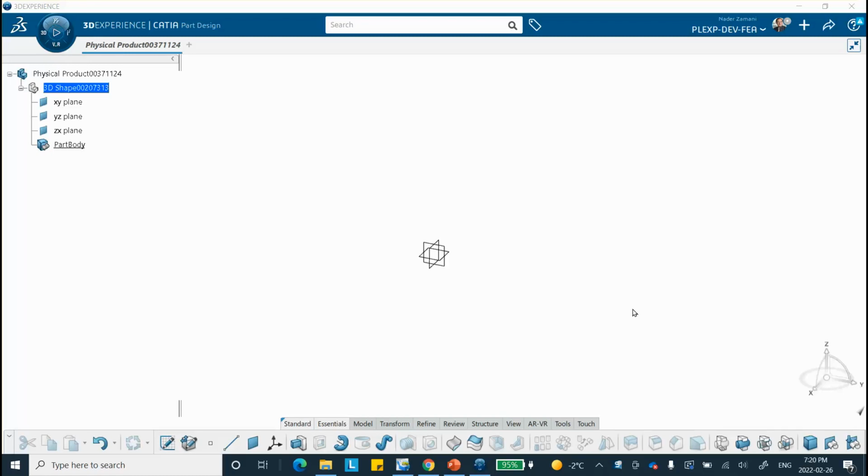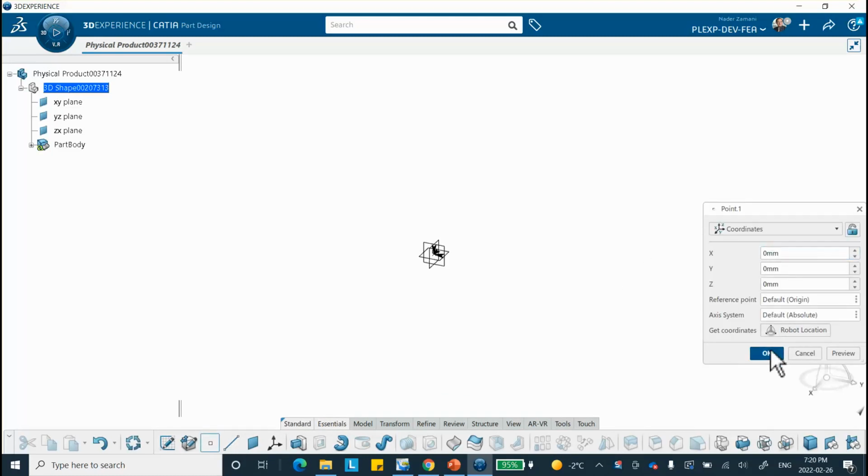Okay, let's go ahead and create this model. So I started with a part file, as you can see. I will create 2 points and the line between them to represent the actual truss member. So 2 points. First one is 0, 0, 0. Okay, the next one is x of 2,499.875, and a height, that's the offset of 25 millimeter.